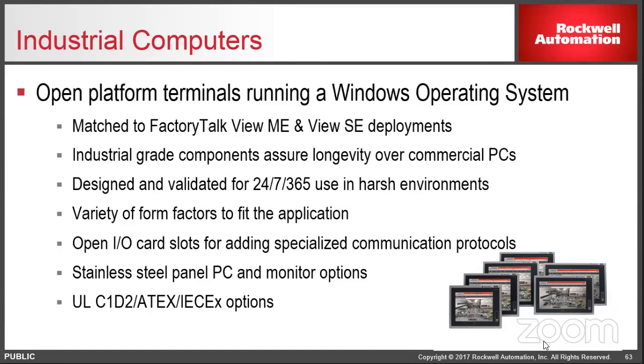It says various forms of communication protocols. Is that a spot for a SIM card or a 4G connection of some kind? That is usually, well, now it's all PCI Express card slots. Think of the Softing PCI Express ControlNet or EtherNet/IP card, DeviceNet, those sort of things. We don't support SIM cards or mini, some of the other form factors. If it's mini or PCI Express, some PCI, we do support some of that.